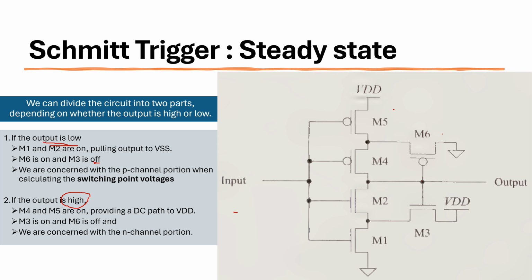So now the second condition is this one. When this is at VDD, and therefore naturally this has to be VSS because it is an inverting Schmitt trigger, right? Another simple inverter for all the reasons. Now what happens? This VSG, VDD minus VSS, is more than VTH on. Naturally this VSG, V source minus V gate, is definitely more than VTH of it, so it is also turned on.